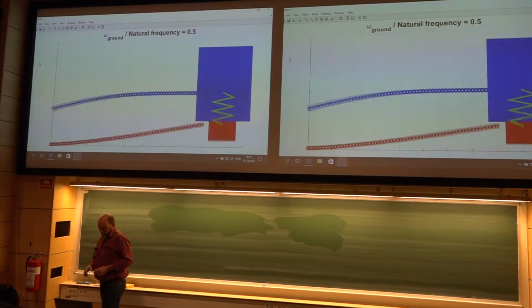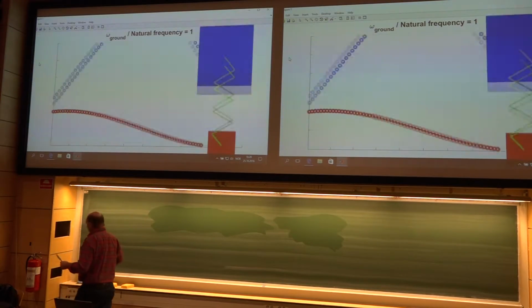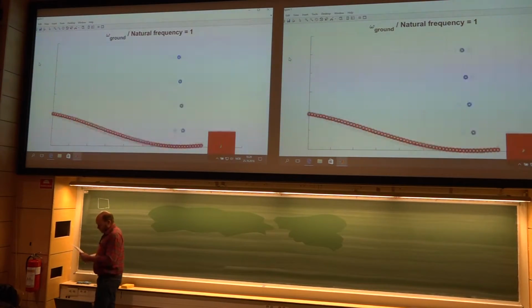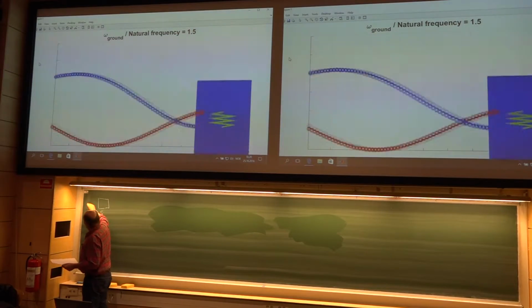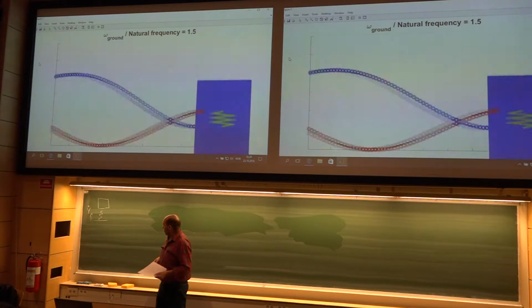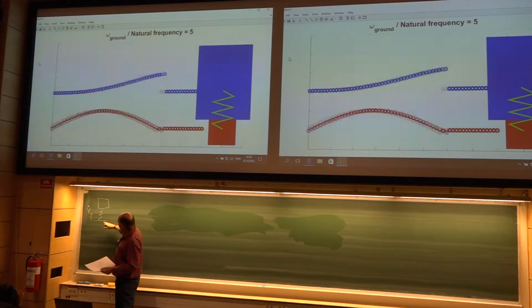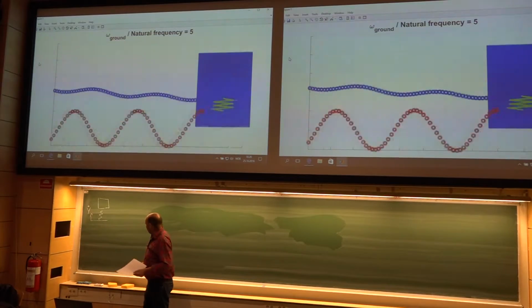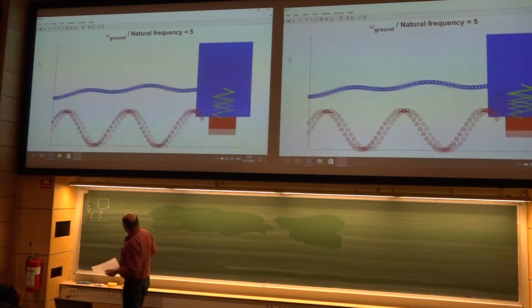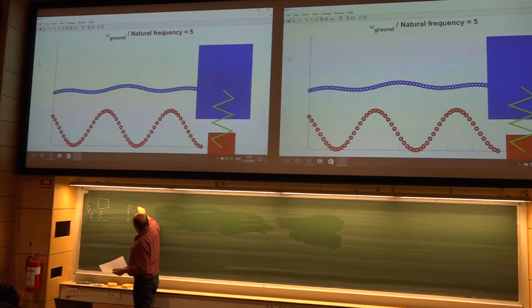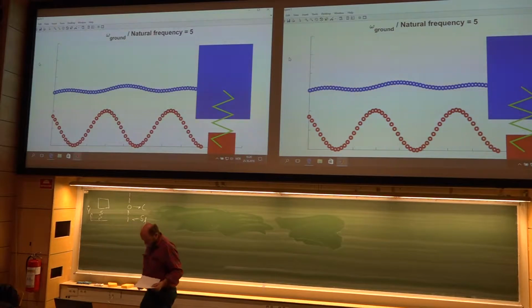And just to repeat, a spring and a mass like this. So here we have some y dot. And what will the bond graph be? Well, you have here something given as a source, a flow source. So that should now be a 1, where the flow source is attacking. Then we have a spring, inserted with a 0, and finally another 1. That will be the position for the mass.